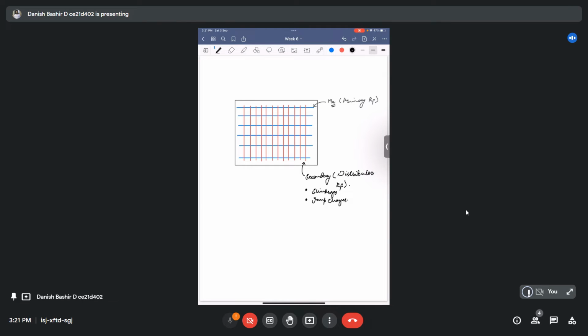Since the depth of our slab systems is very small compared to the beams, columns and other member sections, these slab systems are very prone to shrinkage and temperature change. That's why, to avoid those situations, we provide distribution reinforcement to our slab systems. So there are design rules for how much reinforcement you have to provide as primary and how much as